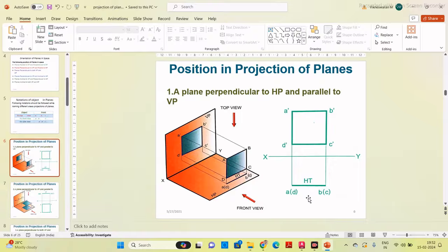Before drawing this horizontal line at the bottom, you have to project a line from each corner of the front view. Here they have projected this light green line, meaning a line without any thickness, from the corners of the square. We have to project these lines and connect both the projected lines, and then you come up with the top view. Simply putting a line is not correct. We have to project lines and then connect the projected lines to get the top view.